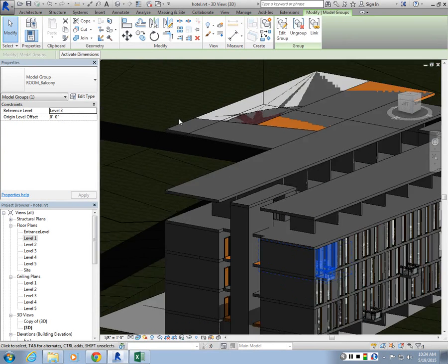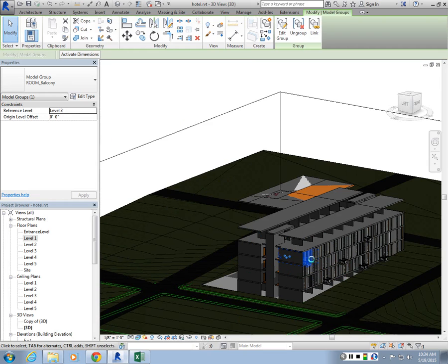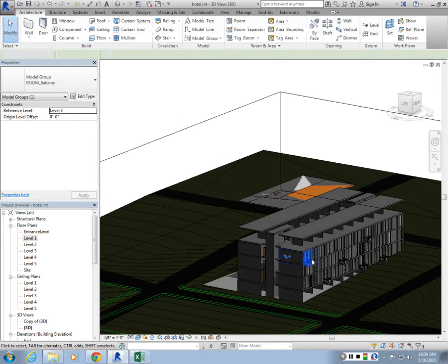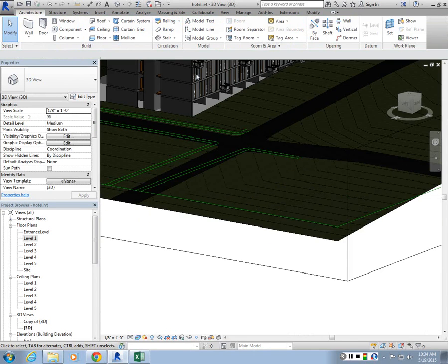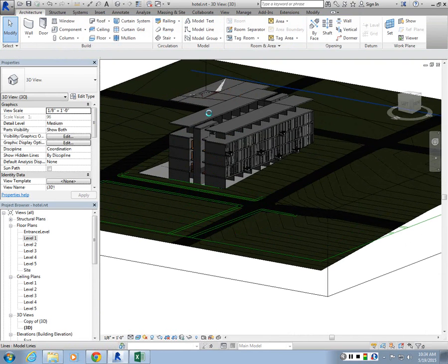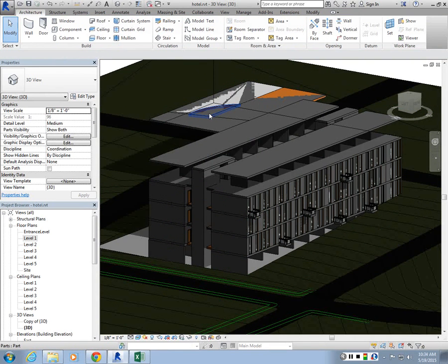I would probably look for it in the forums to see if there's a fix for it. There may be a trick, but otherwise, if you're changing your floor heights, you might as well go through each group and change the total wall heights in that group as well to make it fit. I think that would be a more practical fix for now. Of course, you want to make them go together, but when it's a group, you have to realize it's basically a container. It doesn't recognize the adjacent units around it as much.